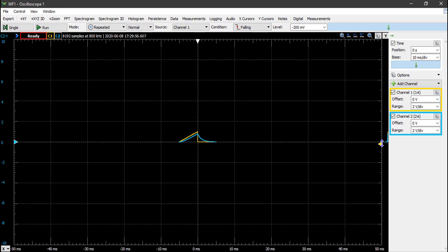Now, in this case, because it's a sinusoid, so we have positive and negative voltages, we can use a trigger voltage of 0 volts. The reason is that we don't know whether it's going to start negative or positive, so this way it'll cover both scenarios.